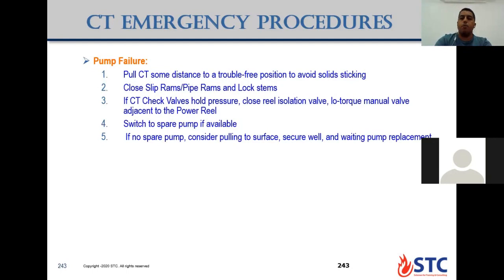If there is no spare pump or backup pump, you need to consider pulling to a safe distance or to surface. This depends on the depth you are running at now. Secure the well while waiting for pump replacement. Then when the new pump arrives, you start to run back to the bottom after you open the pipe ram. Then you continue your operation.